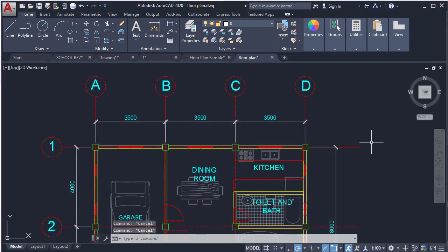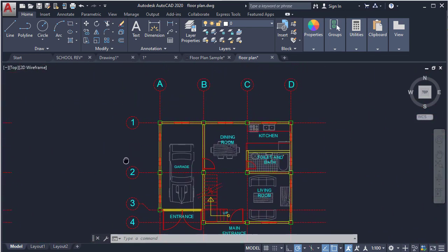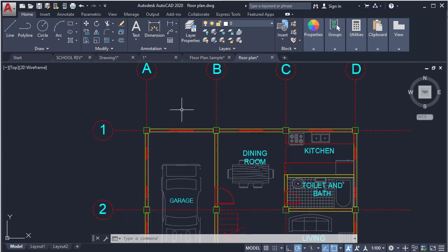If your drawing plan is composed of different scales, you need to create different dimension styles for each of those scale drawings. For example, a scale of 1:100, you need to create a dimension style for 1:100. And a separate dimension style for, let's say, 1:10, you need to create a dimension style for 1:10. An alternative to that is to use annotative scaling. Under annotative scaling, you don't have to create additional dimension style because only a single dimension style will be used for different scales of drawings.